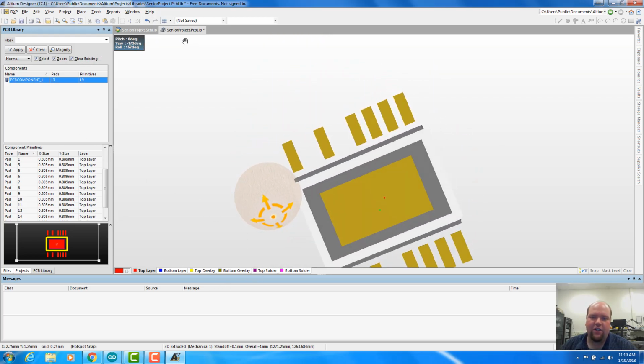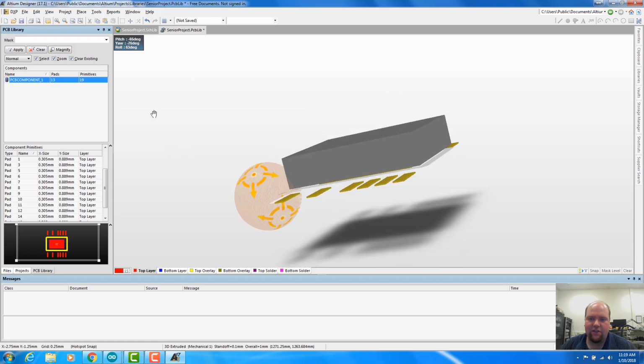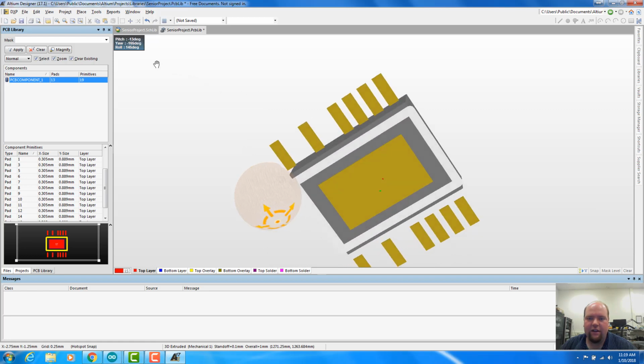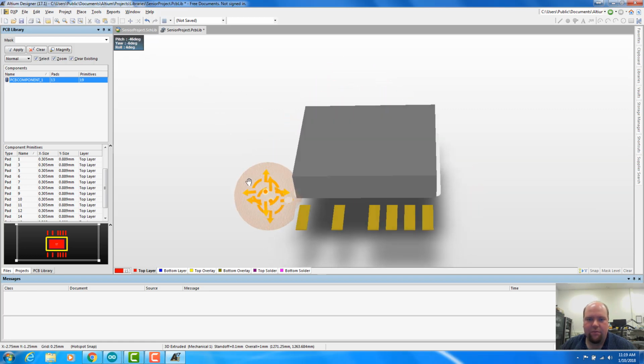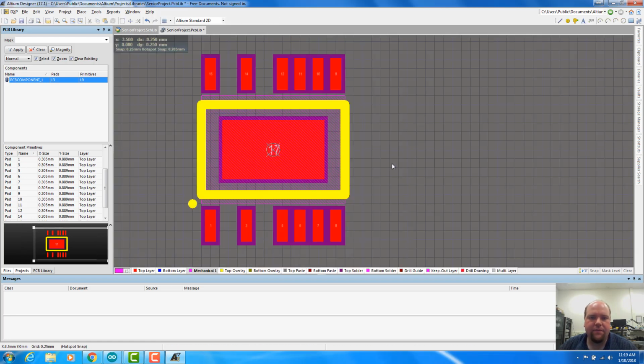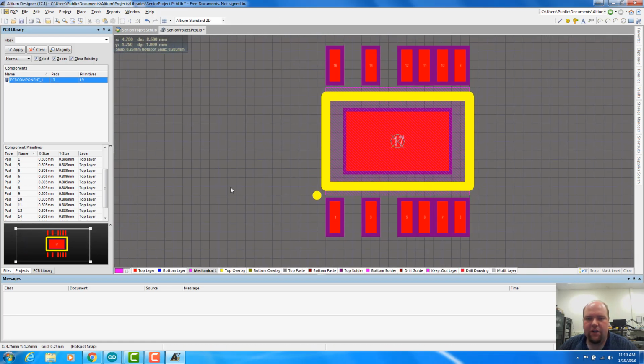And again, this is a way to also confirm that silk screen. So we had that silk screen around there to show sort of the general geometry when we don't have a chip on there. And yeah, it matches pretty well. So some people would leave it just as this. We can add a little more detail. We can add pins in here a little bit. We're not going to do super detailed pins. I'm going to hit the 2 key to go back and realign myself here.